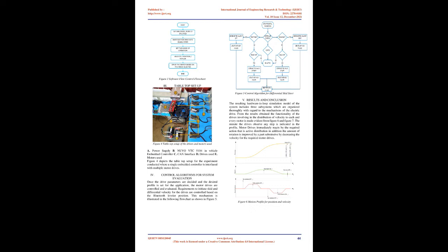For the motion controller, in this scenario, multiple motor drives are connected via the CAN to ensure communication. These drives are equipped with a built-in CAN controller, which helps in communicating with the embedded system for the user application. In this application, a single embedded controller is used as the master CAN controller to interface with the several motor drives, that is NUVO-VTC 5104 with built-in CAN interface.